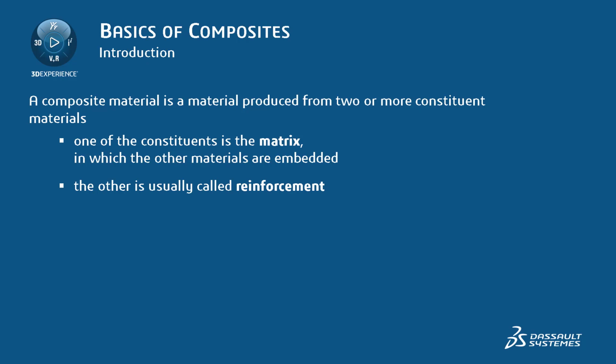The matrix, also called resin, is a binder. It ensures the cohesion of the structure. Resin on its own is good under compression but provides little tensile strength or stiffness. Properties of the resin or matrix include supporting, bonding together, and protecting the fibers, transferring applied stresses and loads, imparting toughness, governing surface temperature, the temperature at which the composite can operate, protecting against the environment, UV rays, chemicals and moisture ingress, and helping adhesion to other parts.